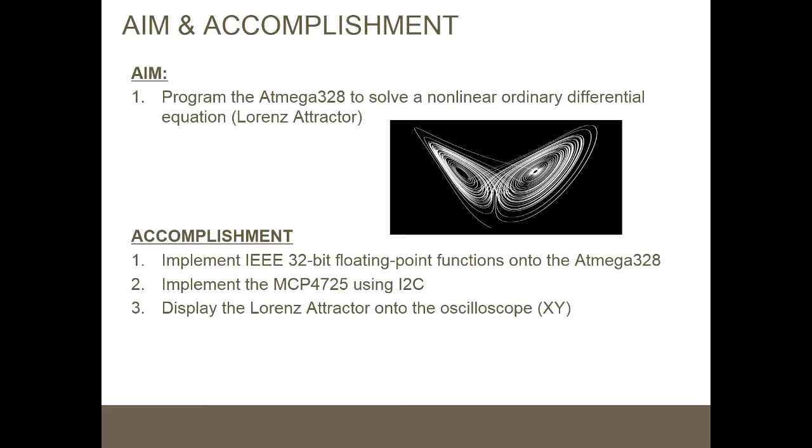I could choose to run the 64-bit format rather than the 32. I picked the 32 for convenience. At the same time, the bigger reason is that the Atmega 328 is a low-profile microcontroller. So having 64-bit means much more computation, and I find that it's just not worth slowing down the Atmega 328 with 64-bit when 32-bit was more than sufficient to solve this particular equation.